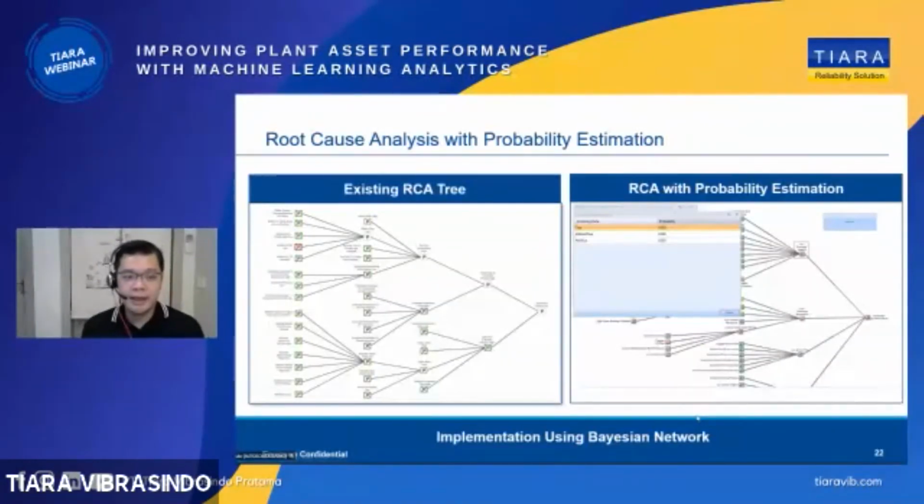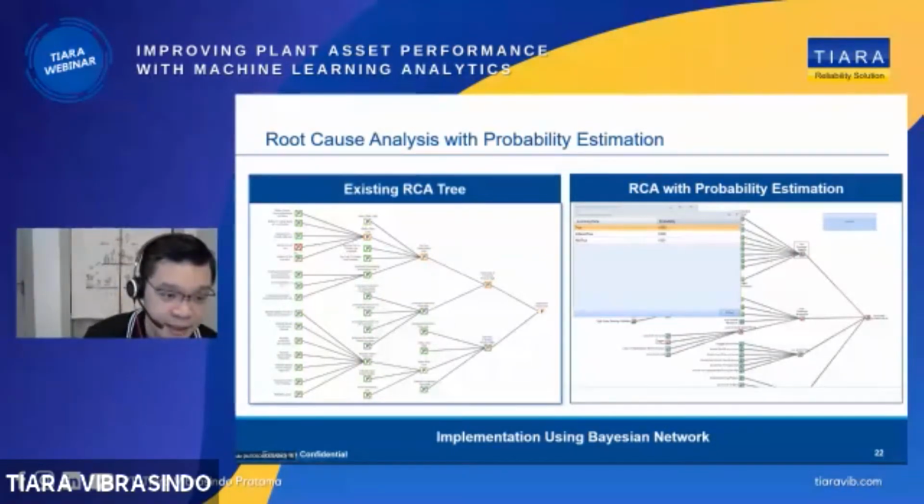Just to show you what actually happens at the back, this root cause analysis is constantly checking, per second, per minute, the condition of the equipment: steam turbines, boilers, compressors, and so on. If it detects something happening, it will start tracing the impact. Or if it detects something that happened in the middle, like here, it will trace down the root cause. So this is an engine that does early detection of abnormality, automatically traces down the root cause, and automatically provides the corrective action.